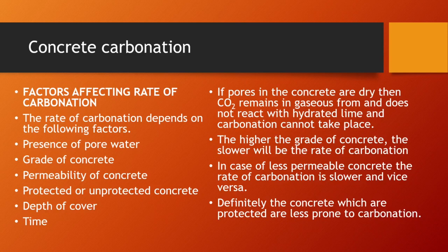When it's curing, there are usually damp Hessian sheets placed over the concrete to control the curing process, the exothermic reaction. And if it's in direct beating sun, you're going to have to do something about it. And then you've got the long-term cover. Is there a protective surface on the concrete that's stopping moisture, vapor, and acid rain from penetrating it?